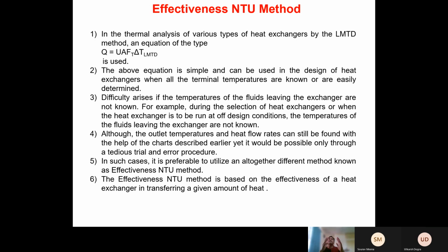Okay, so the same discussion is written here. In the thermal analysis of various types of heat exchangers by the LMTD method, the equation is Q equals U A F times delta T LMTD. This equation is simple, but you require all the terminal temperatures. And if you do not have them, at least you should have a way to determine them easily.